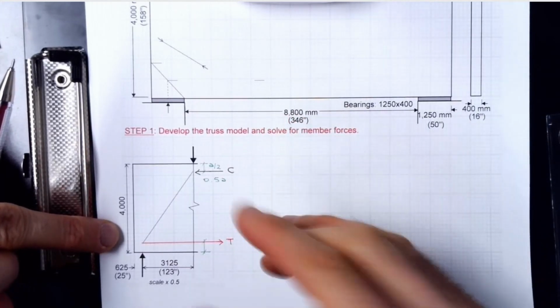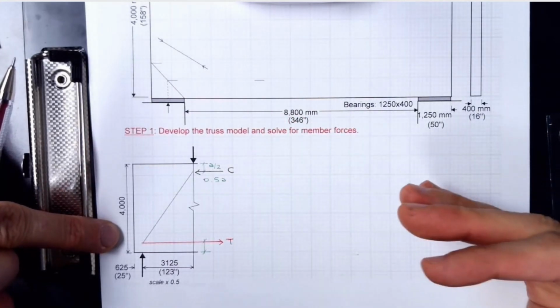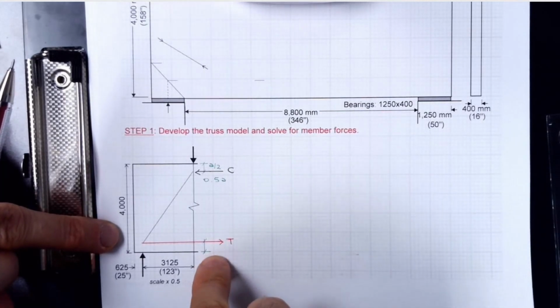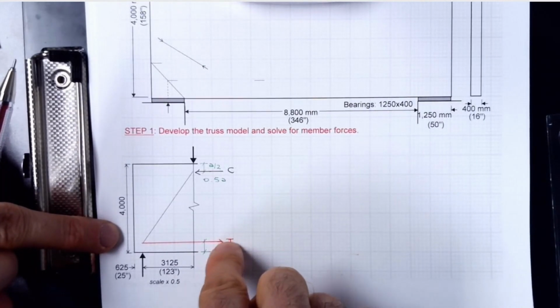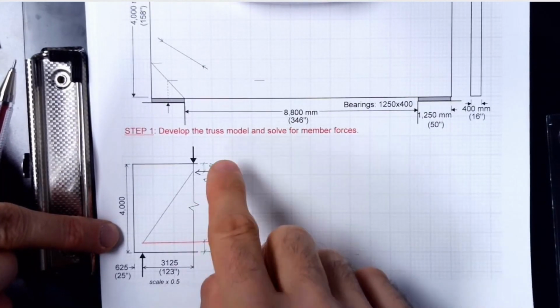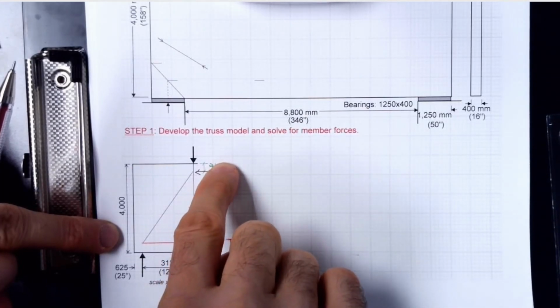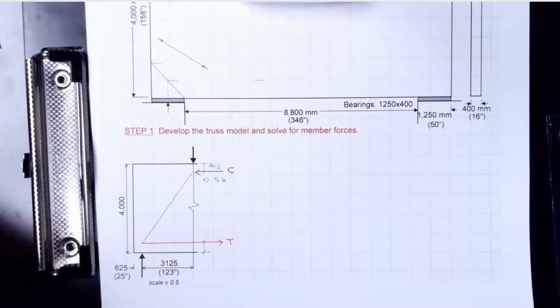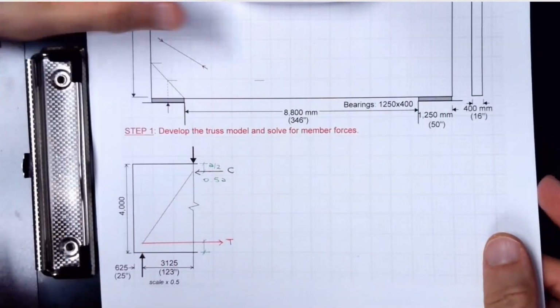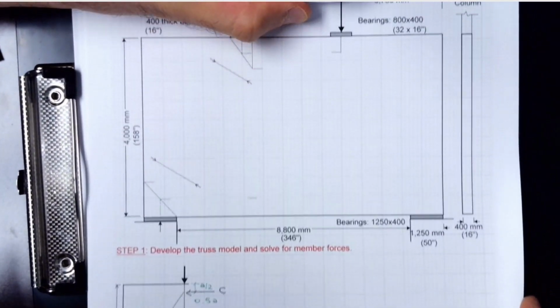If you have a sectional design, if you use your software, and if you know the centroid of the reinforcement calculated by the sectional method, that's a pretty good starting point. You can just give that number here, maybe pick something similar at the top, and that would be a starting point. Usually you might need a couple of iterations, it may not pass.